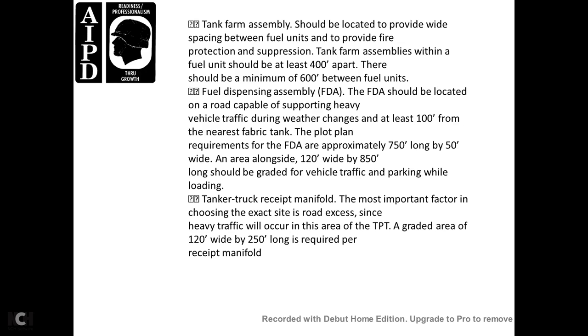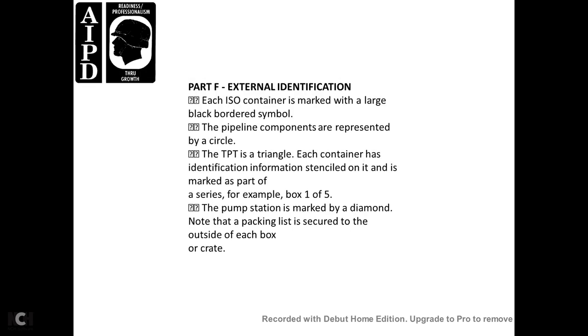The most important factor in choosing the exact site is the road access, since heavy truck traffic will occur in the area of the tactical petroleum terminal. An area 120 feet wide by 250 feet long is required per receipt manifold.